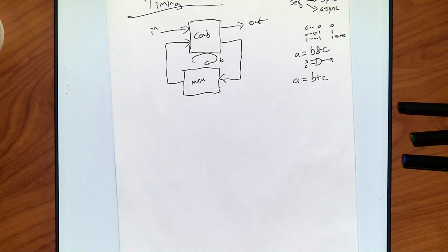If I do it the way most people do, where it's all zeros and a single one, and I get a single event upset that flips that first bit, I have no way to recover. If I'm using all of them as ones, and I get a single event upset, cosmic ray, radiation, electromagnetic pulse, whatever else, and it flips some of the bits, I have a chance to recover, because I can take the majority. Then I've got some protection, which I don't have otherwise. Anyway, that's a side note.